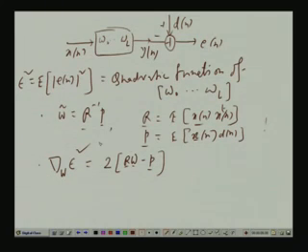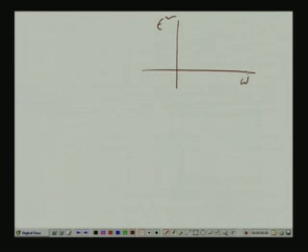We now propose an equivalent technique, that is an iterative technique, called method of steepest descent. Now, to explain that, we first take a very simple case of single coefficient, say epsilon square, say W, only one coefficient. You can easily generalize this treatment to the multi coefficient case, there is not much loss in terms of generality. Now, we know epsilon square is a quadratic function of the filter taps. Here we have got only one tap, that is W. So, epsilon square will be a quadratic function. Any quadratic function has got only one minima or maxima, in our case minima, because we know that there will be a minimum mean square error only.